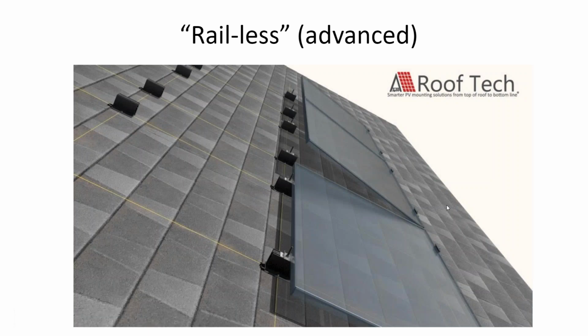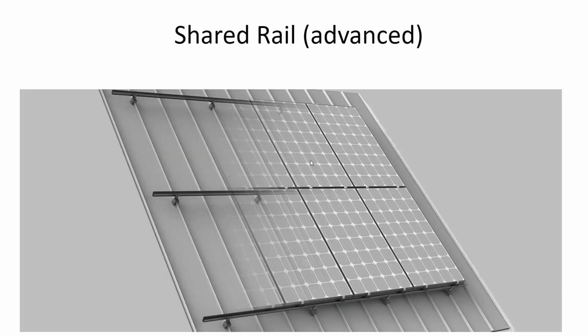And then in California, where they're doing solar all the time, what's popular with installers is railless systems. And railless systems are interesting. I don't like them as much. And the reason is any rail gives you the ability to level the rail. And so if the roof is wavy, the rail has a little bit of give in these attachment points, and it lets you fix that.